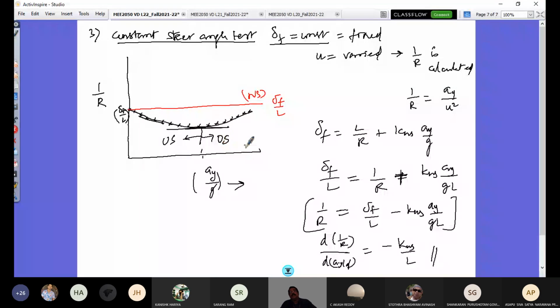Such observation of varying parameters as a function of lateral acceleration can be interpreted with any one of these tests. The OEMs are conducting all these three tests, to complement each other to have the same judgment. Or you can have one test and then have your handling behavior predicted. If you are studying the influence of non-linearity of a tire, what will you do? You take your tire, fix it in a vehicle and do this test. And then you take your competitor tire, fix it in your vehicle and do the test.